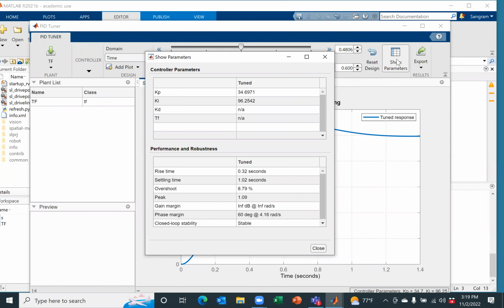Everyone understood this? Now, you may ask me, okay, all this is great, then how do I use MATLAB to design a PID control for my actual robot? Here is what you do. You develop the mathematical model for the robot. For example, the mathematical model would come from Euler-Lagrange. Then you linearize the model. Linearize means find a linear approximation that gives you equivalent results.